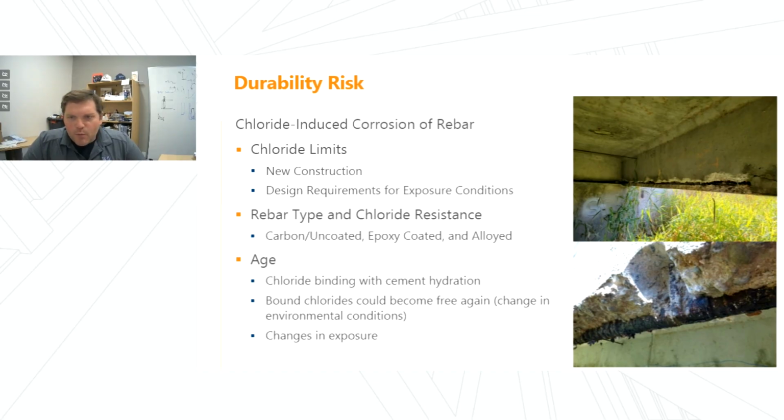And one thing to keep in mind when we're talking about structural risk is that it's not just a single static target. As structures age, there's a lot of potential for changes in exposure, which could lead to more chlorides being added. Obviously, chloride contamination builds up. But there's also the concept of chloride binding.